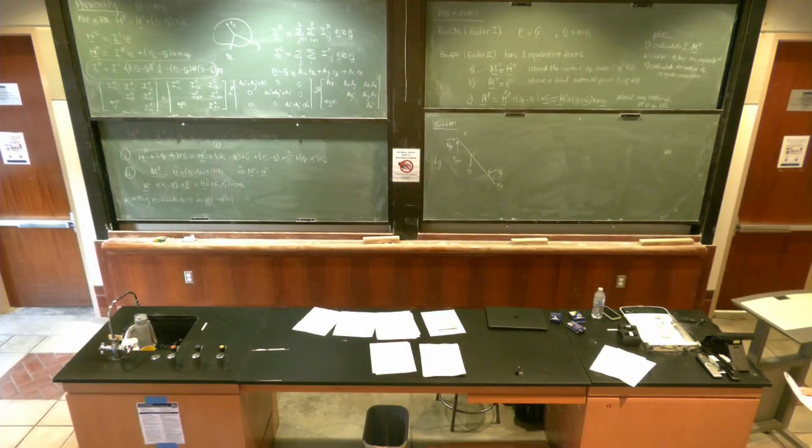Now, because the rod is about to tip forward, what happens to these forces? What is equal to 0? Exactly. The rod is losing contact at A, so the normal force at A is 0. And if you were to decelerate a little bit more, the rod would tip over, right? So the rod is barely in contact at A, so that's why NA and FA are 0.